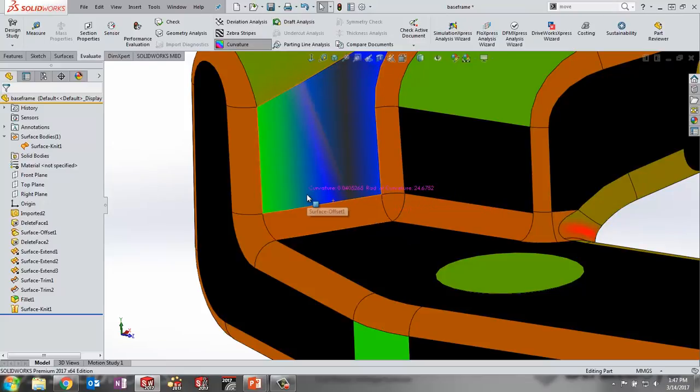So in this case, what we did is we went in, copied those surfaces around the area that was a problem. We extended those out, trimmed them away, and then used the fillet tool to go in there and refillet those or recreate that geometry. This was some geometry that necessarily couldn't be patched. We couldn't delete that face and patch it back together, but we could go in and fix it with a manual approach. To fix that using solids, you'd have to cut out that section, then try and put it back together. So using surfacing, an approach like this, is essentially your only approach to getting this done.